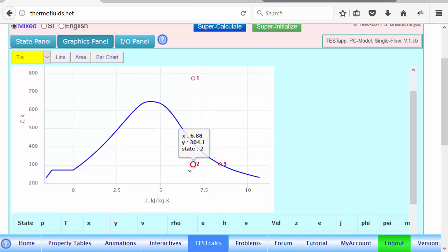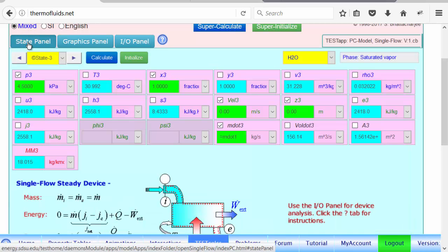But there is another kind of ideal turbine. Suppose we say, you know what, state 1 and 3 are the actual inlet and exit, and we don't want to mess with that. Can we make the turbine any better? Yes, and that's called a totally reversible turbine for the given inlet and exit conditions. Such an efficiency is called exergetic efficiency.